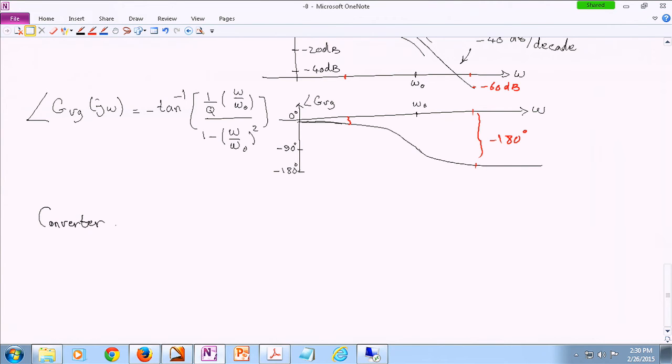All right. So let me draw the table, then I will tell you what these parameters are. They have a definition which is G sub G naught, and G sub D naught. G sub G naught is the DC value of the audio susceptibility transfer function, and G sub D naught is the DC value of the control to output transfer function.